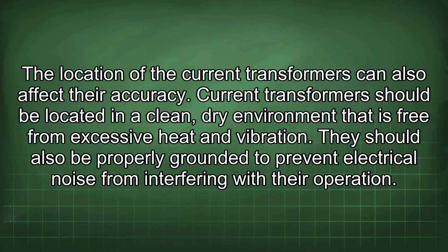The location of the current transformers can also affect their accuracy. Current transformers should be located in a clean, dry environment that is free from excessive heat and vibration. They should also be properly grounded to prevent electrical noise from interfering with their operation.